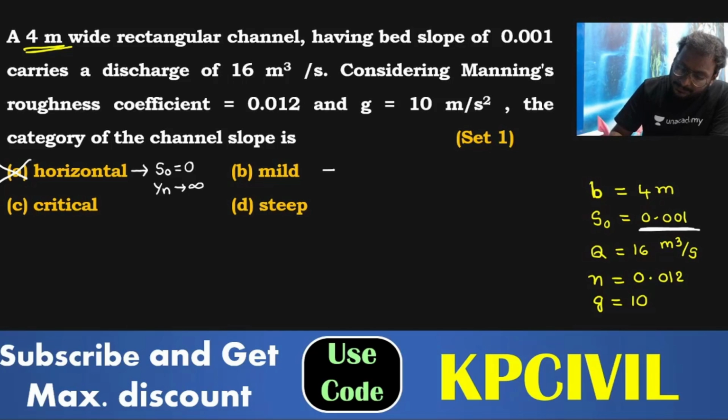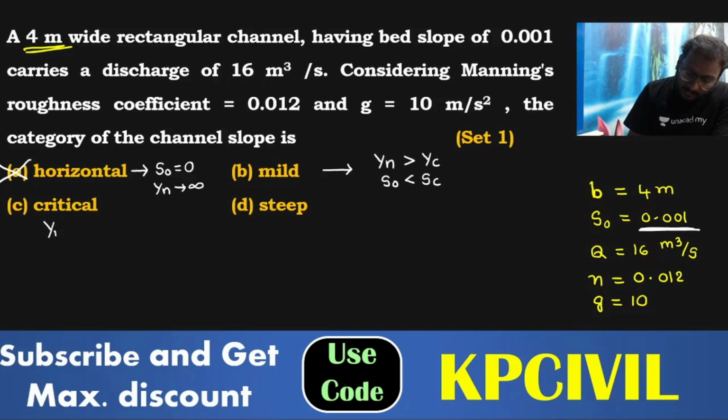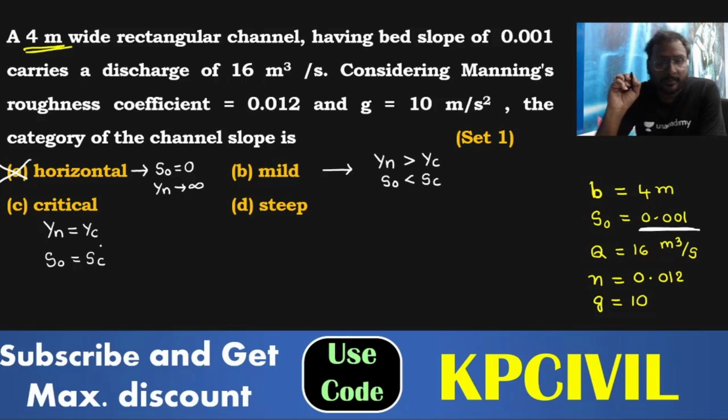For a mild slope, you can prove normal depth greater than critical depth, S naught less than Sc. If any one is proved, your question is completed. For the critical condition, Yn is equal to Yc. Critical depth and normal depth are same, S naught and Sc are same. Yn is equal to Yc, S naught is equal to Sc for the critical slope condition.